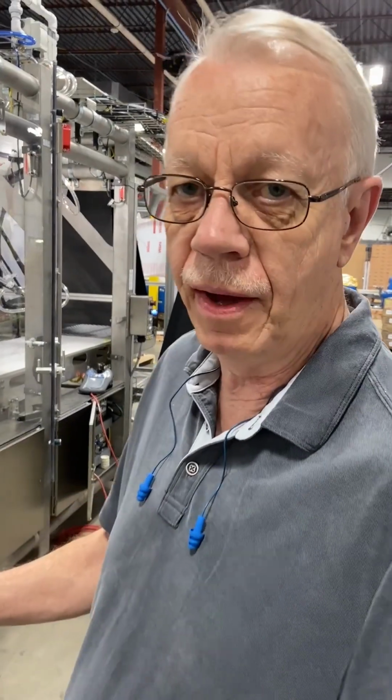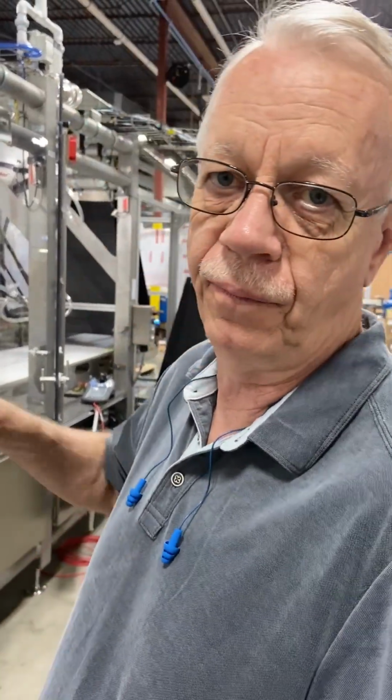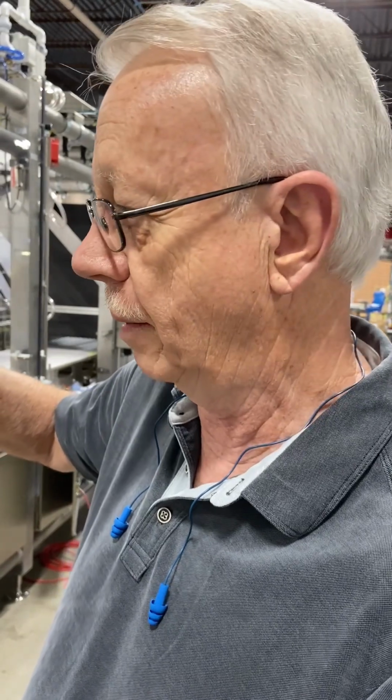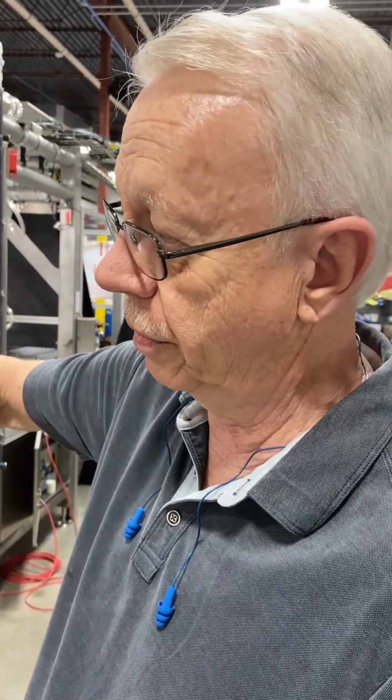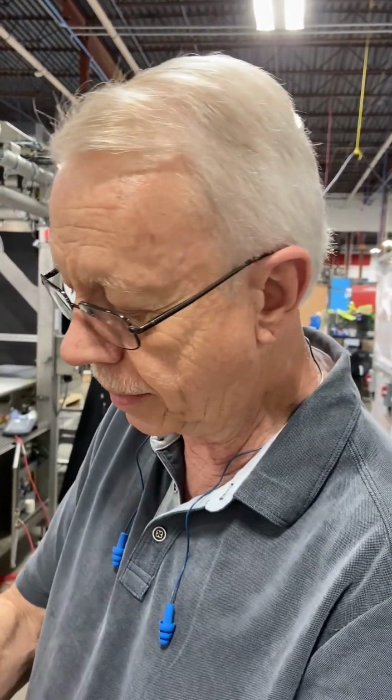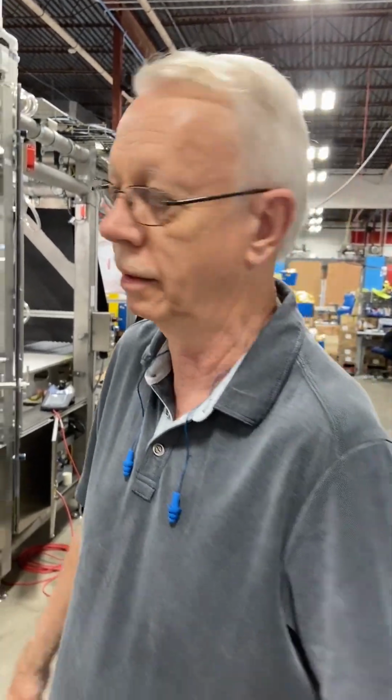Okay, we're going to finish up the calibration now, and the first thing we need to do is connect the belt. Sometimes it doesn't connect, so what I'm going to do is manually rotate the encoder wheel a little bit, and then the program will see that the encoder counts have moved, and it'll probably connect.